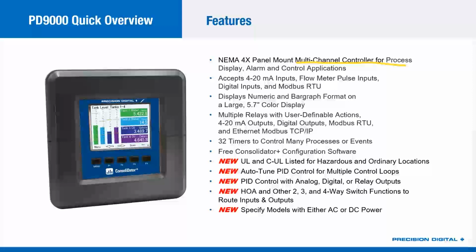And it can also have 4 to 20 milliamp outputs and relays. So that gives you the ability to do alarming and control, as well as signal conditioning, and you can send that information back to your SCADA system, however you'd like. So there's a lot this product can do.